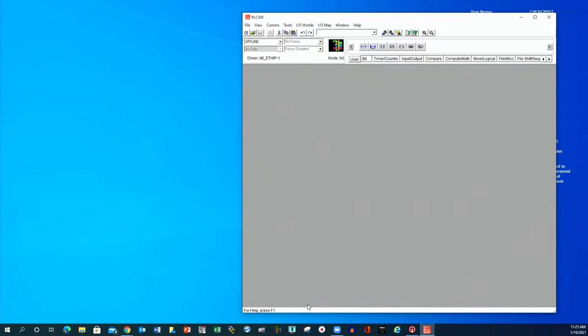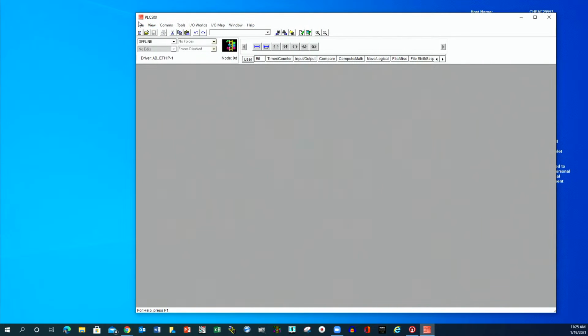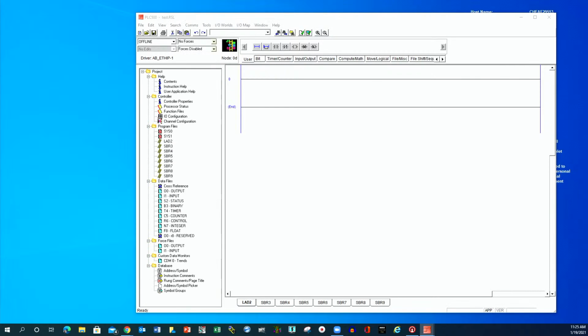Okay. The next thing we're talking about is a jump instruction. We talked about this previously when I did my intro. Basically, this is a way to jump around a program. So I'm going to do the same thing and open up the software. I hope it's done. If this does it again, I will definitely go over it. Okay. So a jump instruction allows you to jump within or around a program.